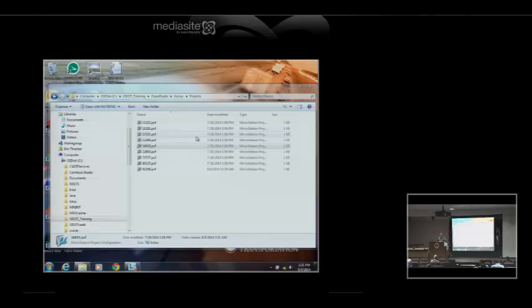Yes, you can use the inverse factor to go back to grid if everything's on ground. We had, I think, some data in District 7 that had been surveyed a few years ago, and it was on the ground. And we're bringing in some new data that was on the grid. So we made a ground factor and said this is where it's at. It's on ground, and then brought in the grid data, and it lined right up.